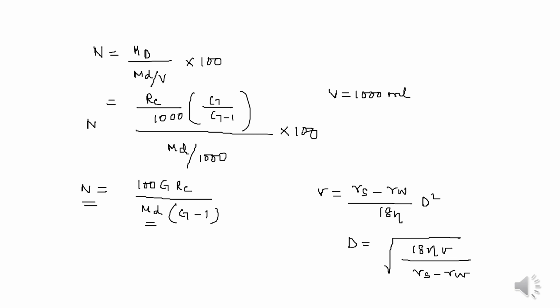So if the soil particle of the diameter d we are concerned with is falling through a height of He in time t, right, we can find out the velocity. So the velocity is equal to He by t, right? So we simply replace in this relationship of d the viscosity, velocity and unit weight of solids and unit weight of water.